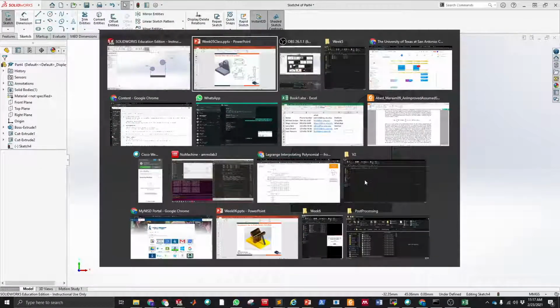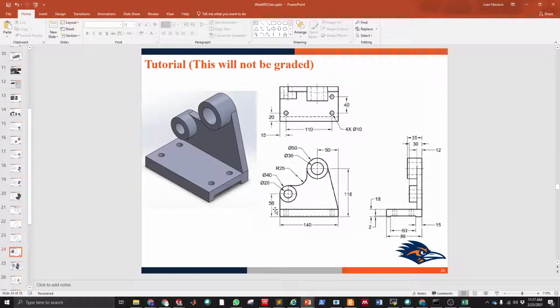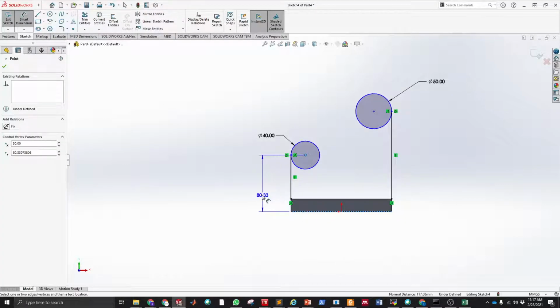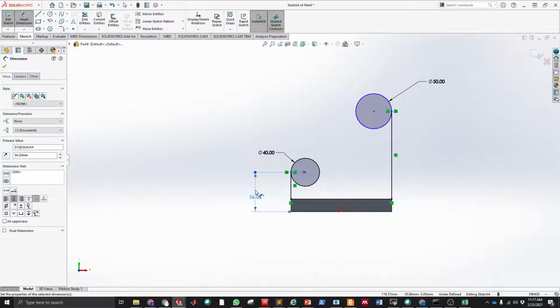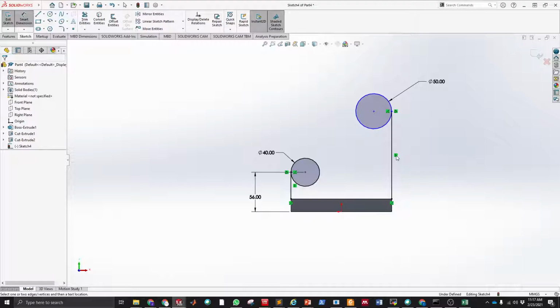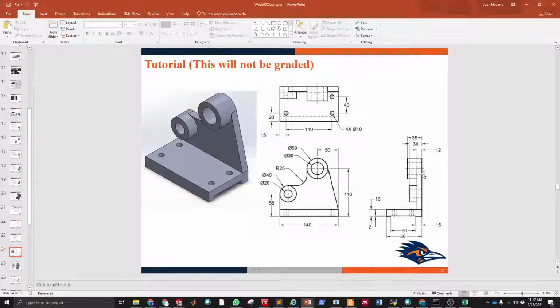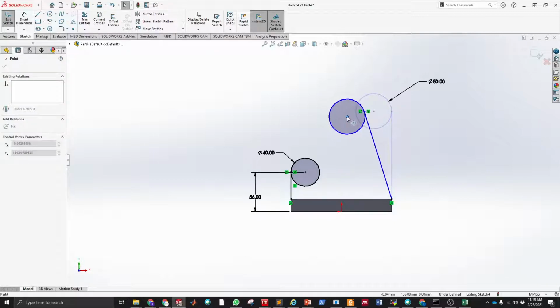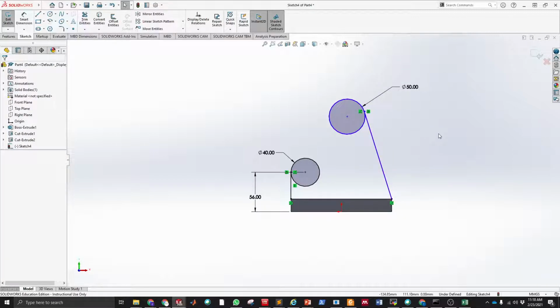We know this height is 56, so we can define that, 56, and we also know this 118. Now, this relation, this line is not vertical. As you see here, it's actually at a certain angle. So I can just click the relation and then click delete in the keyboard. And then I can move this one around. However, this other one that is tangent, that one holds.